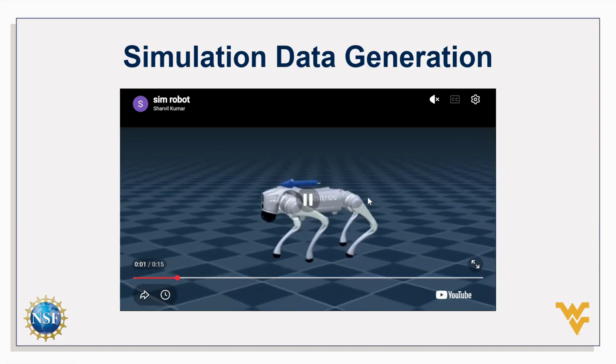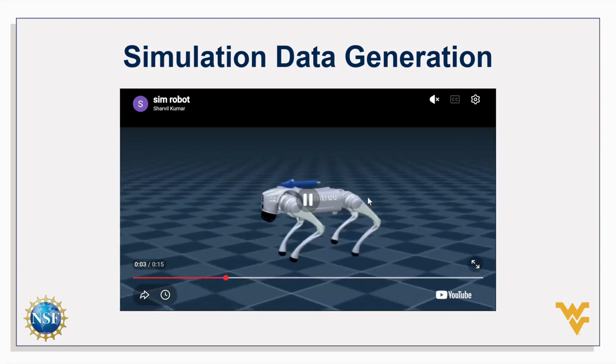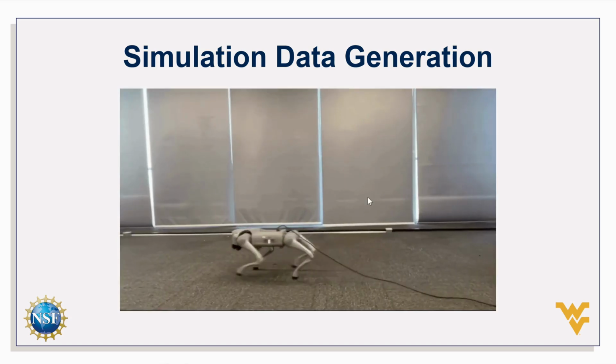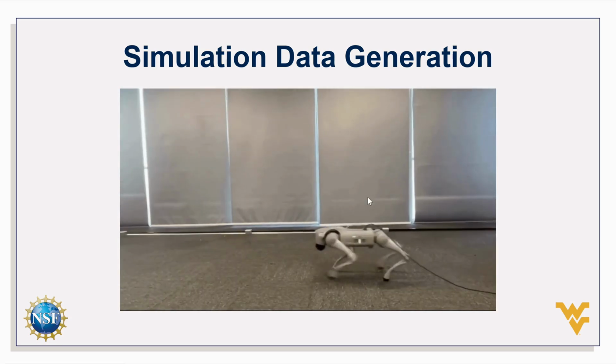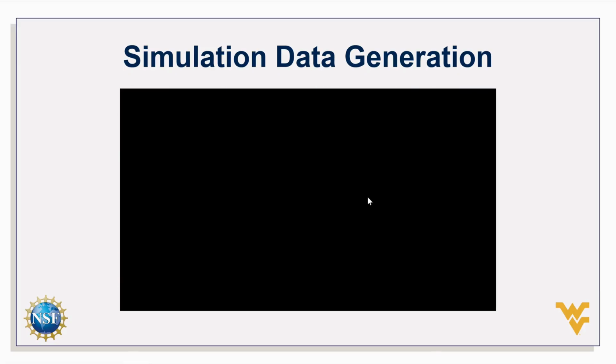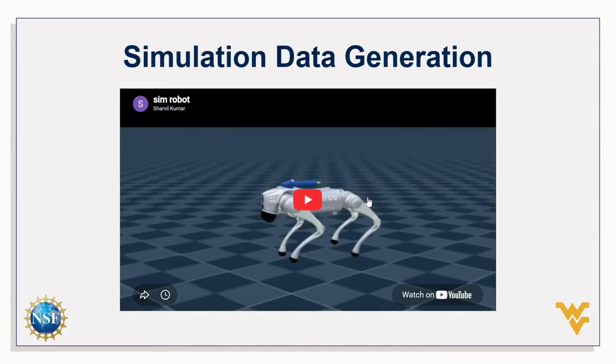We used the high fidelity physics simulator IsaacSim to create synthetic training data to use in our CNN, to simulate 2,000 trials of varied motion and diverse friction conditions with an emphasis on low friction environments. Simulation allowed us to collect large amounts of labeled data before testing on the real robot in a time efficient manner.